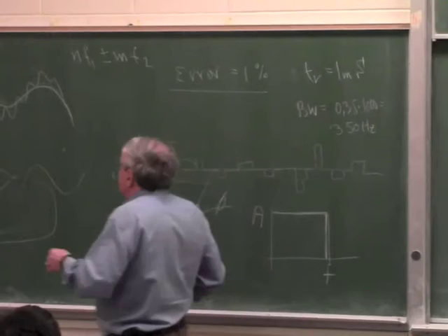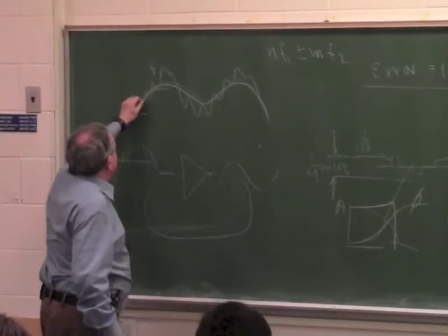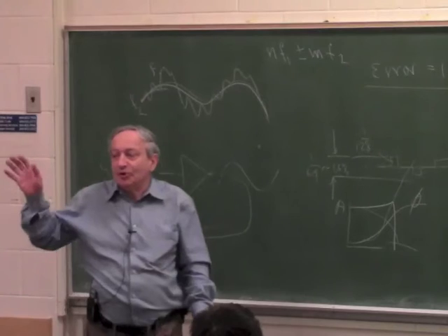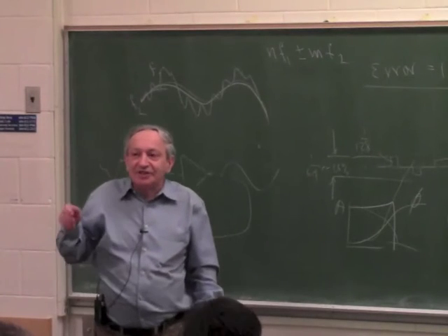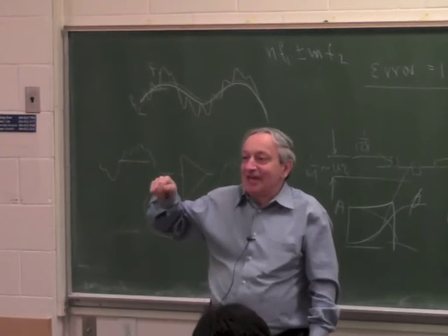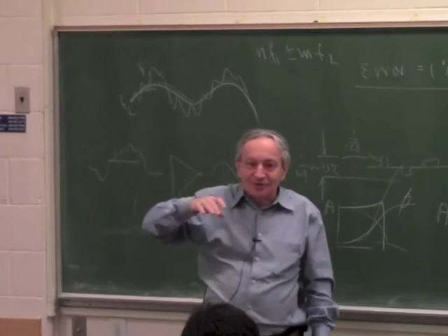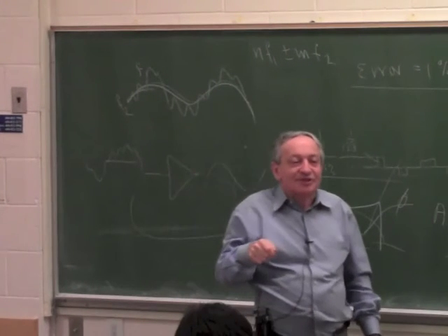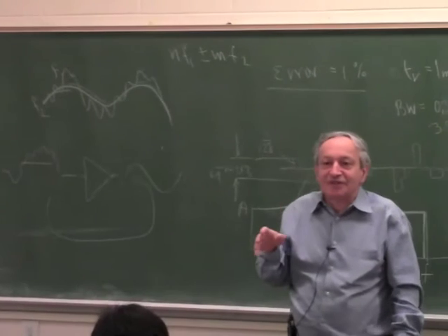So let's say your signal is 1 kilohertz, but there is a 1 megahertz sitting on top of it, say from some radio broadcast. That's very common. Every signal you look at, you can see about 1 megahertz sitting on it, because that's the AM bands. And then you can also see like 100 megahertz sitting on it. And if you have a good enough scope, you can see there's actually 1 gigahertz sitting on every signal.